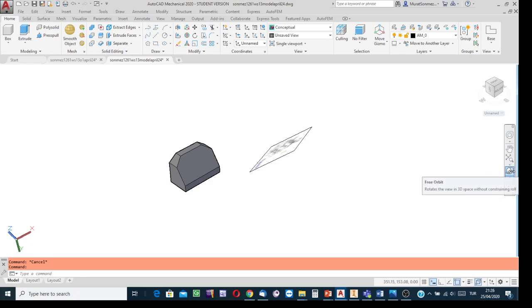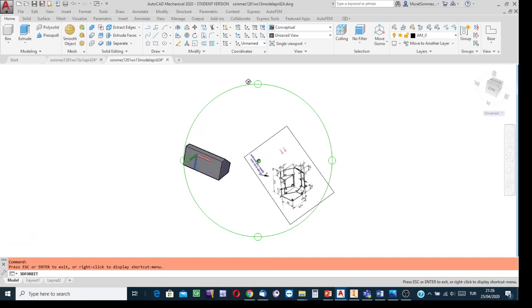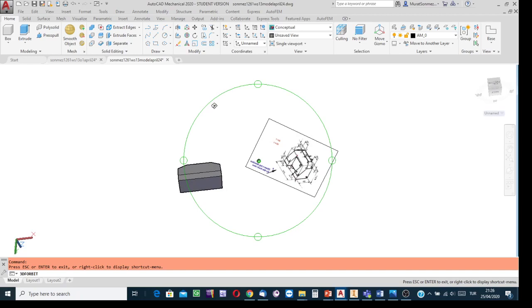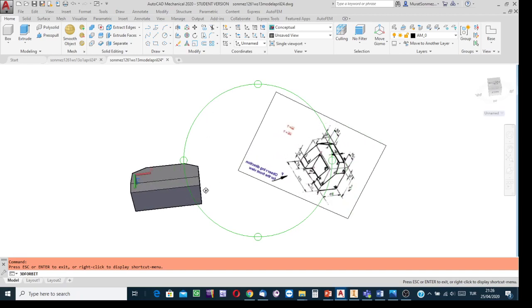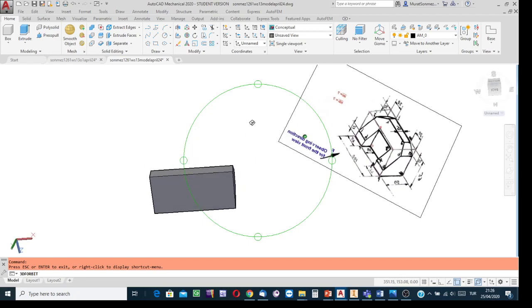Bottom side surface: enable you to see the bottom side, rotating the model. Okay, see the bottom side surface. And then, since I'm going to draw the edges of the surfaces of the channel on the bottom side surface, I know the XY plane must coincide with the bottom side surface.